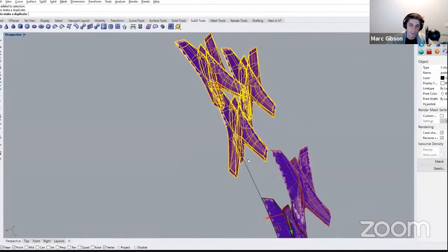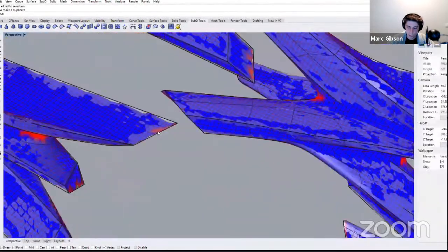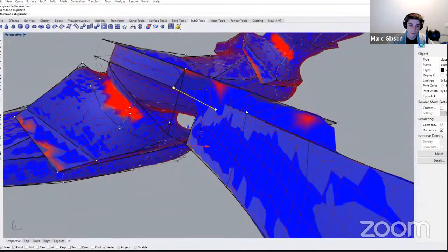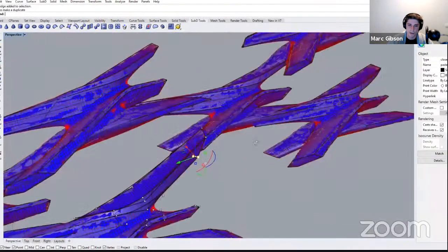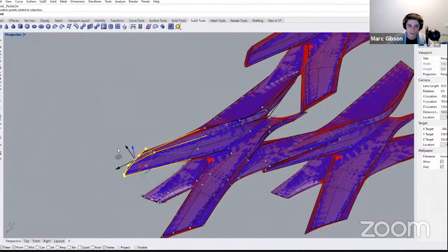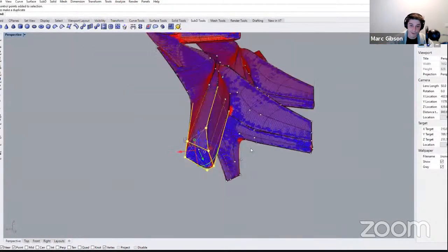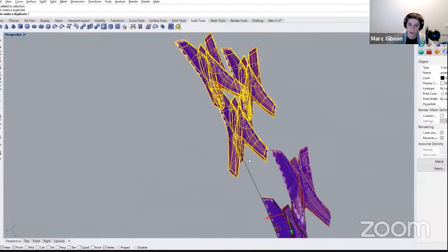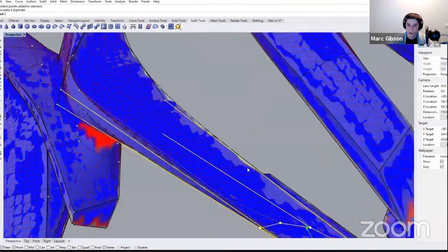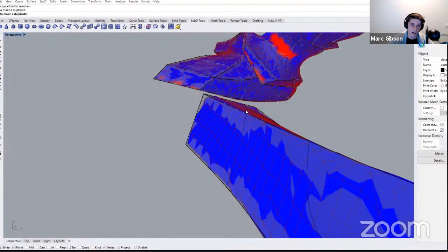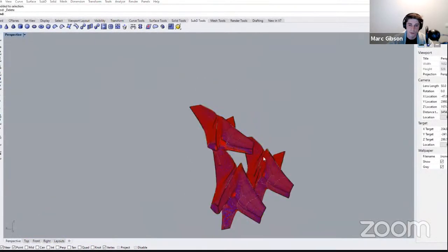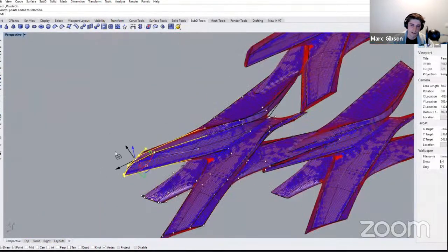Generally the reason why we do this is because with our design process, we like to have control over the top-down design properties as well as the algorithmic, and have an interaction between the two. Now on screen here, you can see we're operating on a fairly low resolution sub-D model of a bit of geometry, and we're roughing out to figure out the parameters of what we're working with here. On top of this, we're visualizing what the higher resolution geometry would look like when connecting for a 3D printed form, whilst running the layers of draft angle analysis.